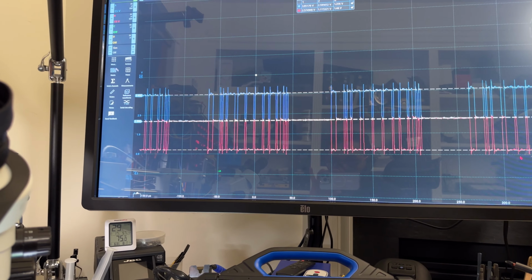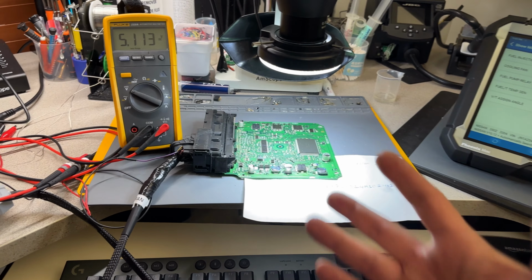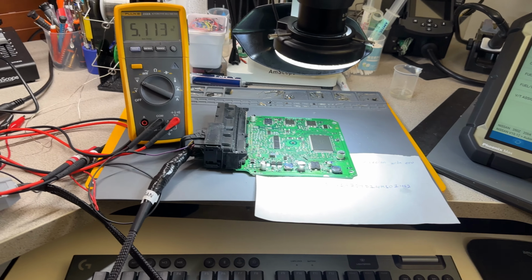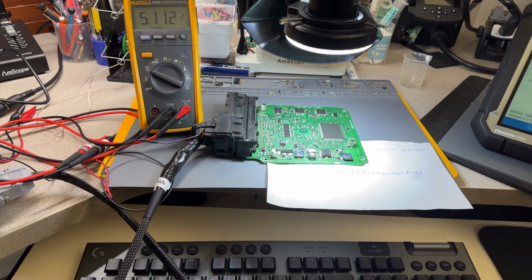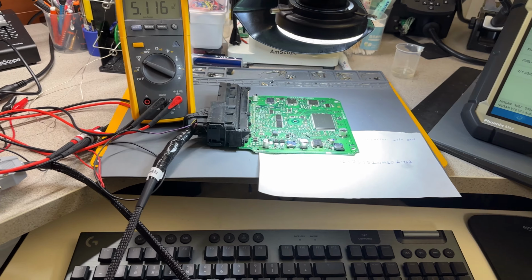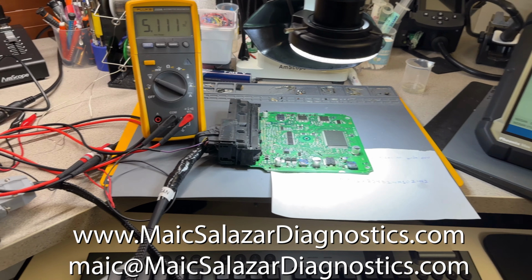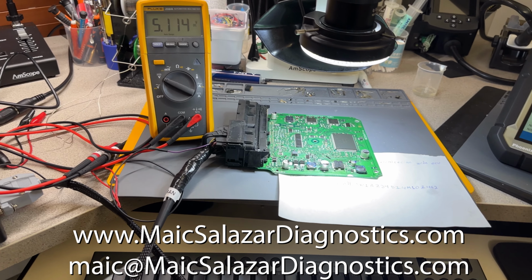And again, it's something that I can use in communicating here because I don't have the rest of the car, so this computer wasn't able to communicate because it's connected to the entire bus. The bus sees and the computer tries to activate the rest of the components, and that's what it was shutting down. So his diagnostics, or whoever did the diagnostic, was completely correct, and I'm fixing it.